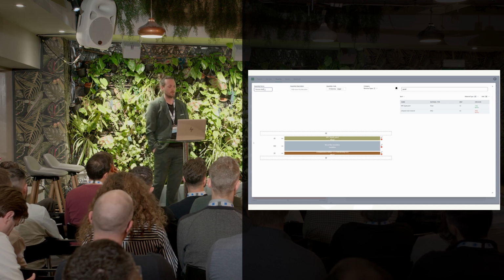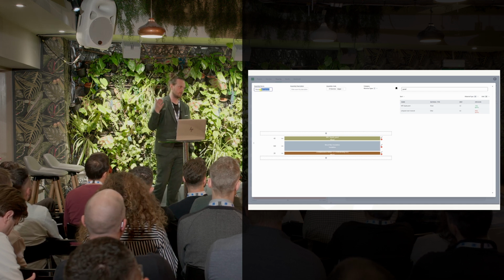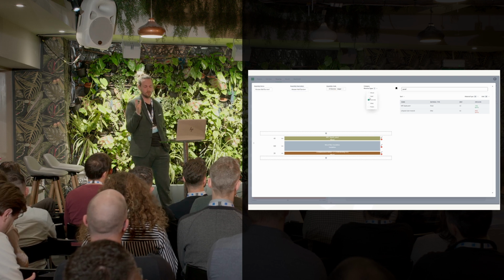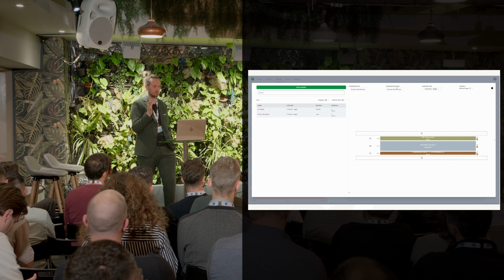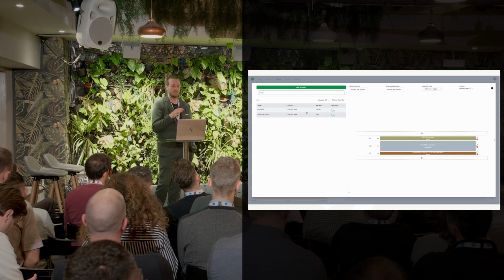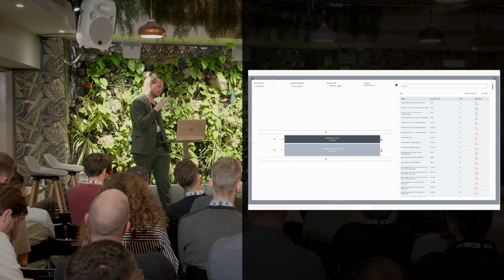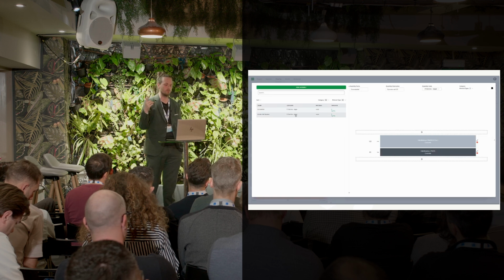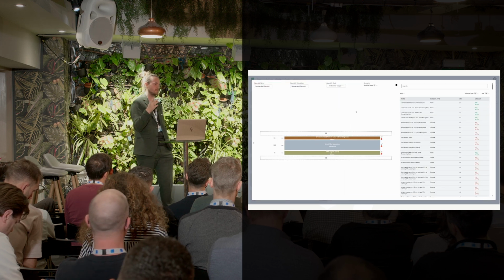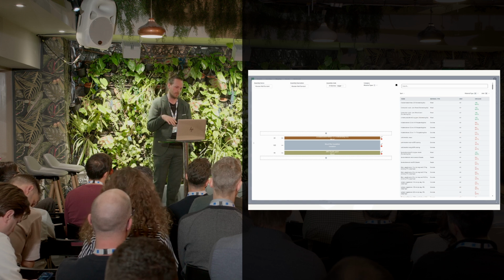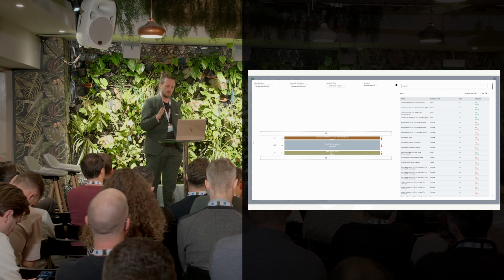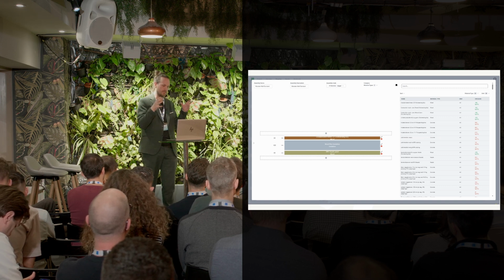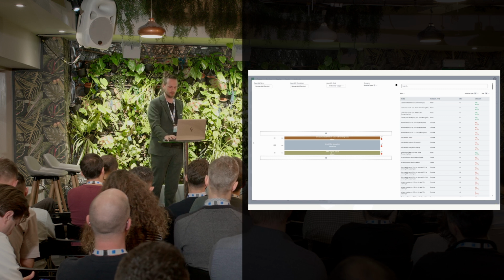But since we're using most of the time Rhino data for early phase, which doesn't have building part codes and stuff like that, which you need for carbon emission calculations if you want to certify it, we're setting it on these materials as well. So every time you apply this towards a generic object, it becomes, for example, an external load-bearing wall, because it knows that this is the construction of an external load-bearing wall. So it's quite easy, and you can split these. You can calculate them as one big thing or split them out in their parts as well.